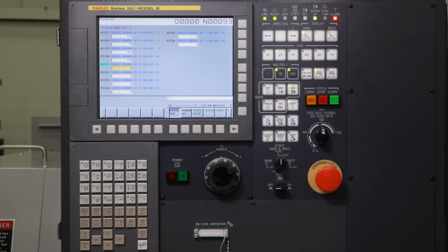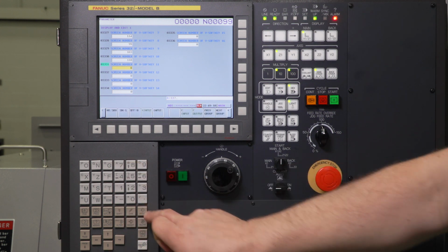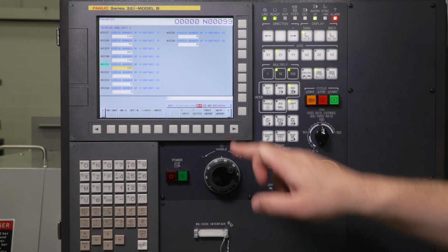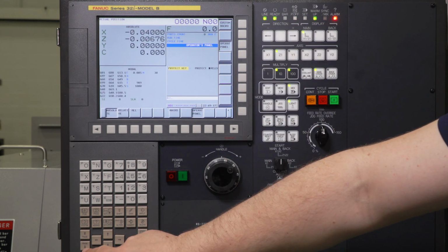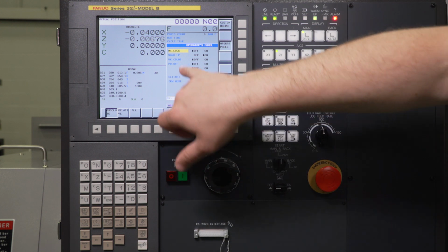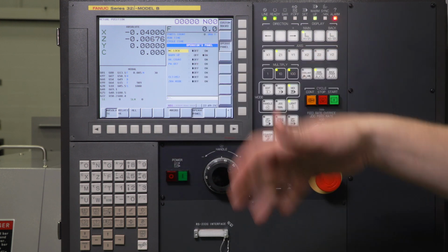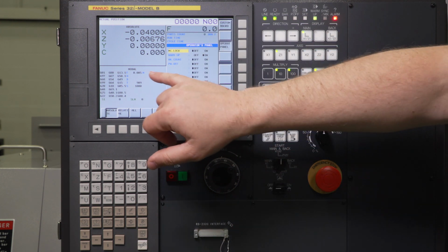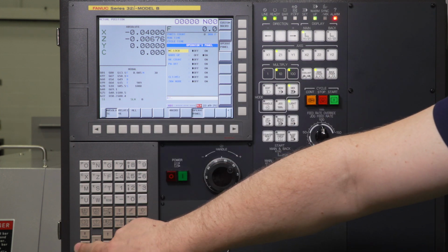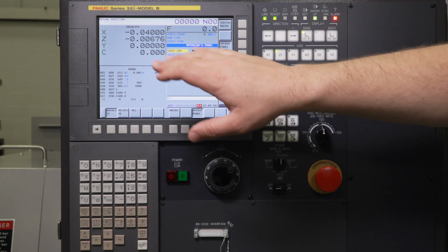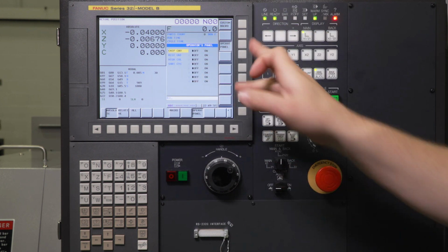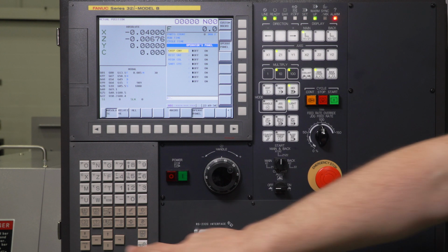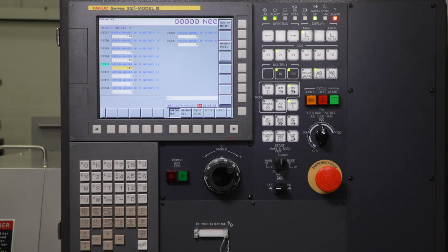3331, we're going to make a 117, which is going to be operator's panel. Now this is a custom panel for the Tsugami itself. So we go to operator panel. That's going to bring us to our protect release. It's going to bring us to turn on our warm-up mode, which is going to be if we don't have a bar feed attached, our zero return mode, and chip conveyor, mist unit, high pressure coolant, and short cycle. We can turn all those on or off right from the operator panel. That saves us about 3 keystrokes by putting it in this vertical menu.